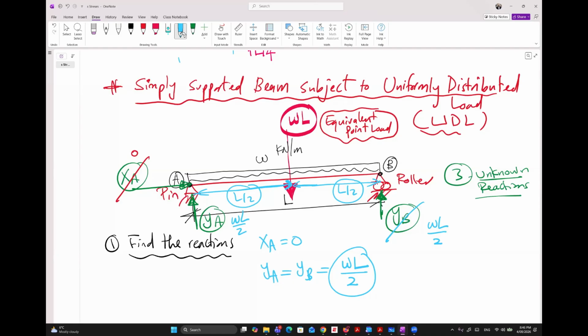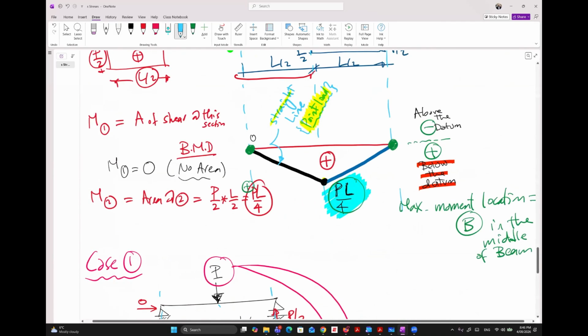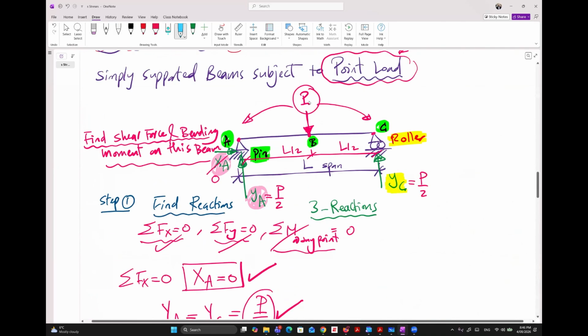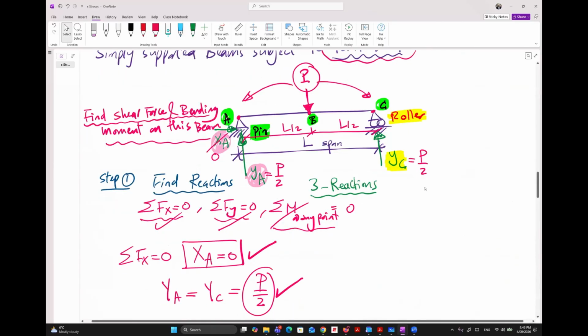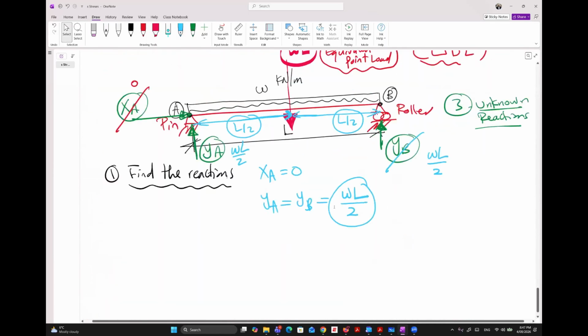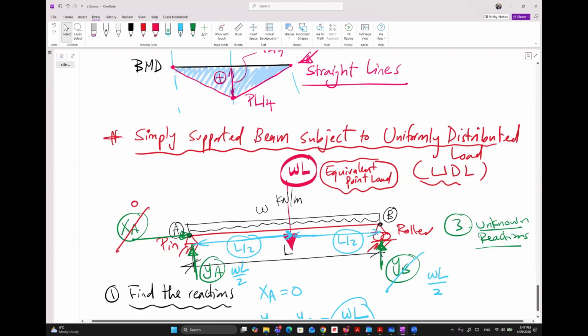Yep, makes sense. Okay. So what is the difference in the interpretation of these two problems? Here we have the load directly in the middle, so half goes right, half goes left. Here the load is distributed. So to be able to deal with it, we first concentrate it by multiplying the uniform load times the distance, or the span.